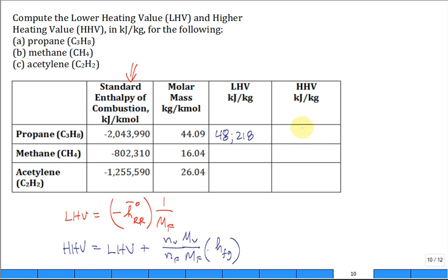Anyway, for the propane, you find this is 49,908. So it's greater. So somewhere in between is reality, because you probably aren't going to get all of that unless it comes out hot. If it comes out cool, some of that could be below the dew point temperature of the products, and water would like to condense.